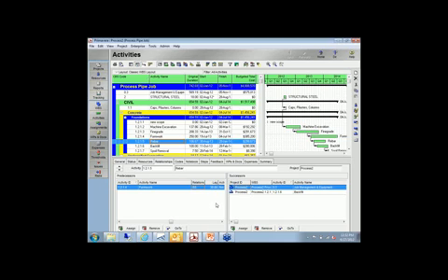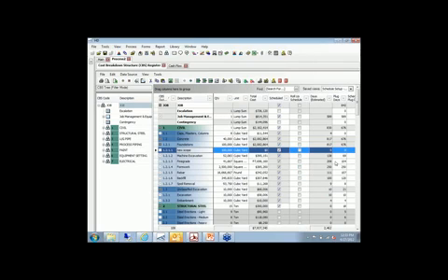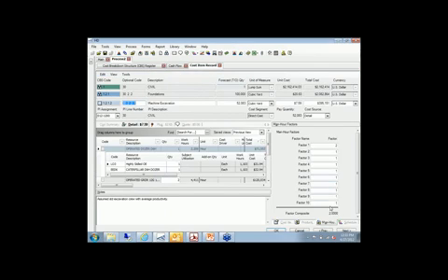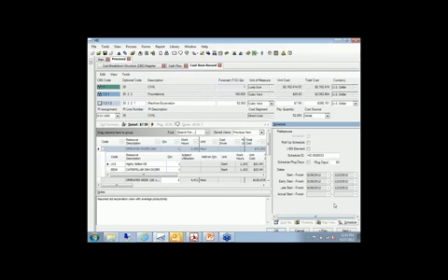Now, if we come back to hard dollar, if you look at the start and finish dates for all of these items, let's drill into any particular item, let's take machine excavation. We can turn on columns for the information I'm about to show you, or we can drill into that item. Here's a nice little schedule tab where we can see for this machine excavation all the dates we brought back from Primavera. Okay, so the scheduled start and finish dates, early start, late start, those all came back in from Primavera. And so we can use that information to help drive lots of things.